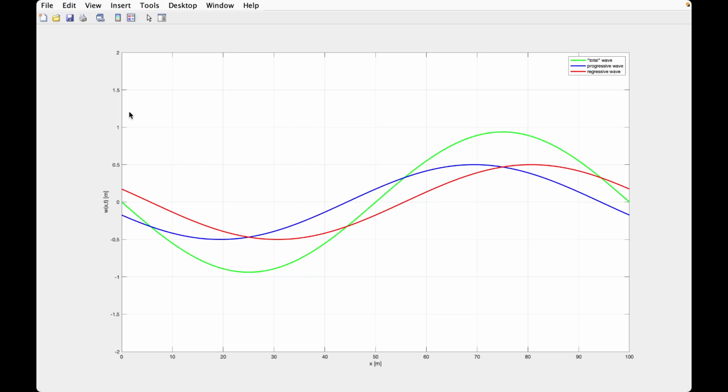And so please be aware of what you're doing, which are the quantities that you're using. Be aware that the propagative velocity is this quantity here: the sigma of the material multiplied by the load factor with which you are using the material, divided by the density of the steel, all right? And so it is increasing just because the maximum sigma is increasing and we are going up with the load factor. But the maximum load factor is 1 when we are breaking the steel because it is too loaded.